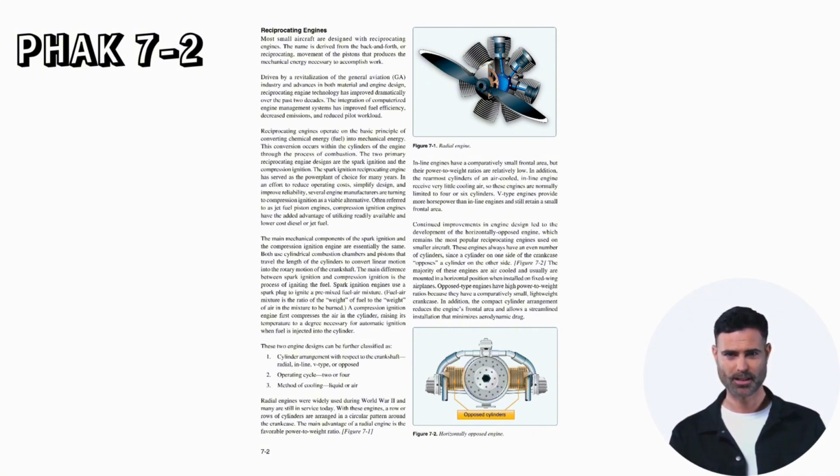Fuel-air mixture is the ratio of the weight of fuel to the weight of air in the mixture to be burned. A compression ignition engine first compresses the air in the cylinder, raising its temperature to a degree necessary for automatic ignition when fuel is injected into the cylinder.